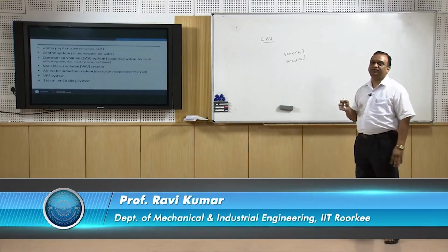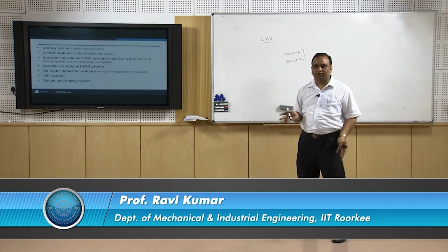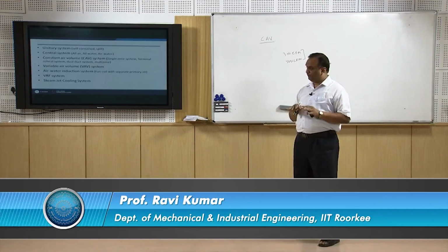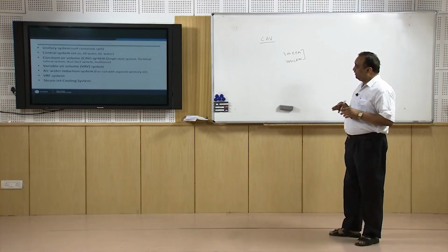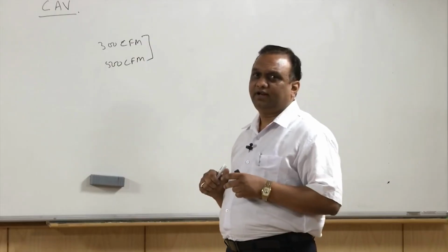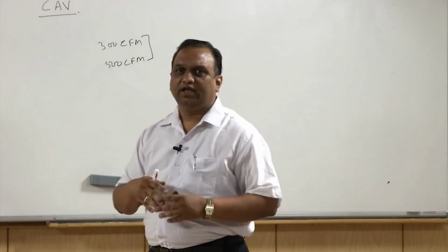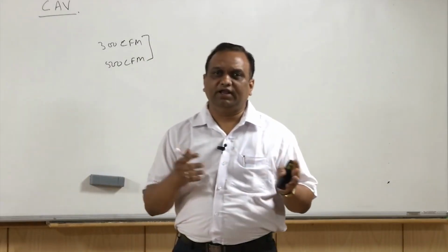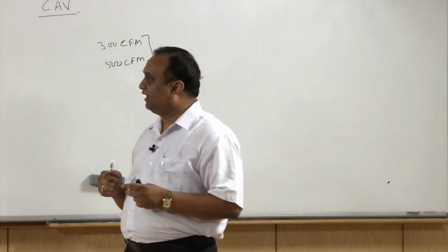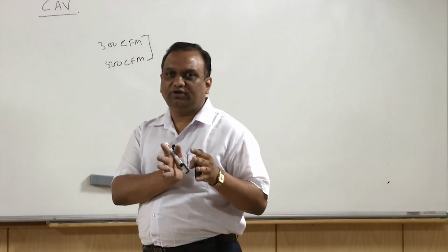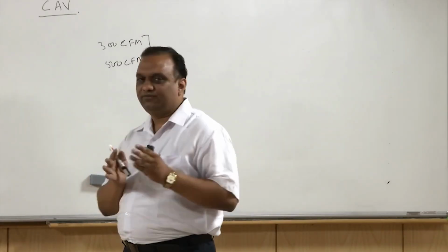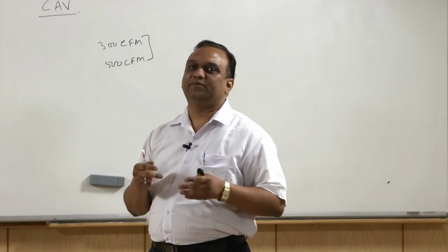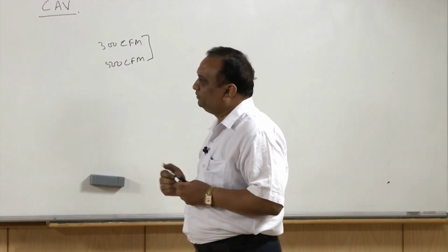The constant volume system can be a single zone system. The single zone can be a single room or multiple rooms or even a floor. A floor can also be a single zone. Now, in different zones, different environmental conditions can be maintained. That is why in big buildings, normally, zoning is done, right. And for each zone, normally for all air system, there is a separate expansion device.